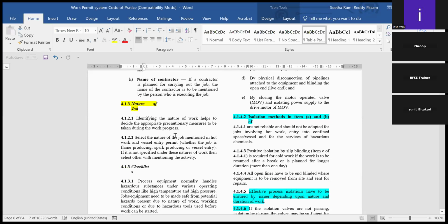Then nature of the job. This is very helpful. Based on the nature, whether it is hot work, height work, excavation, confined space entry, vessel entry, or electrical work permit, it helps us decide the appropriate precautions and measures to be taken during the work progress. So if it is an excavation, if you go deeper and deeper...